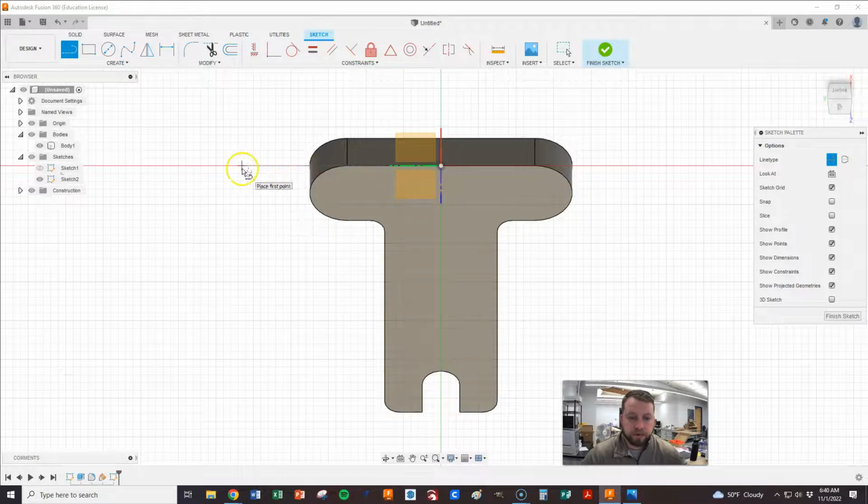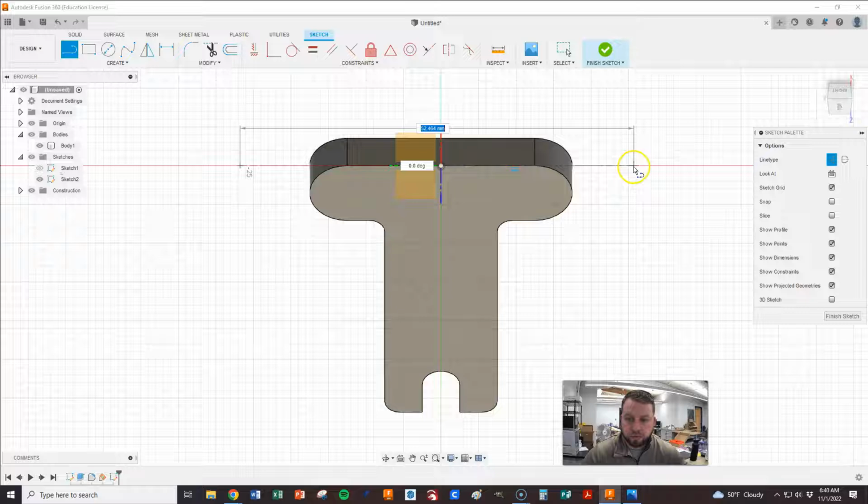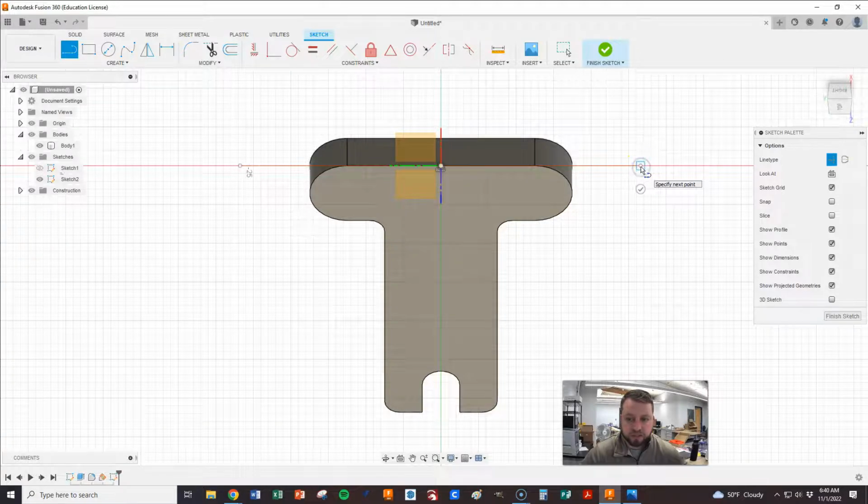I'm going to take my mouse out there so that I hovered so that it knew I wanted to be in line with them. I'm going to click there. So see, I've got a line started. It goes right into the origin and through, and I'm going to take it past. So it doesn't matter the distance. We just want a nice horizontal line that goes through the origin all the way across. And so now, when I turn my construction line off, I have something to reference. See how it'll stick on that, and I can start my drawing from that?